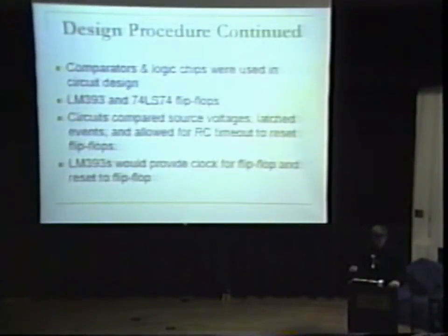As I said, the chips used were comparator and logic chips, the LM393 and the 74LS flip-flops. The LM393 was used to compare the voltages, and when the voltages for each source dropped below a certain threshold voltage, there was a latched event followed by an RC timeout to reset the flip-flops. And the LM393 comparator would provide the clock for the flip-flop and reset it.